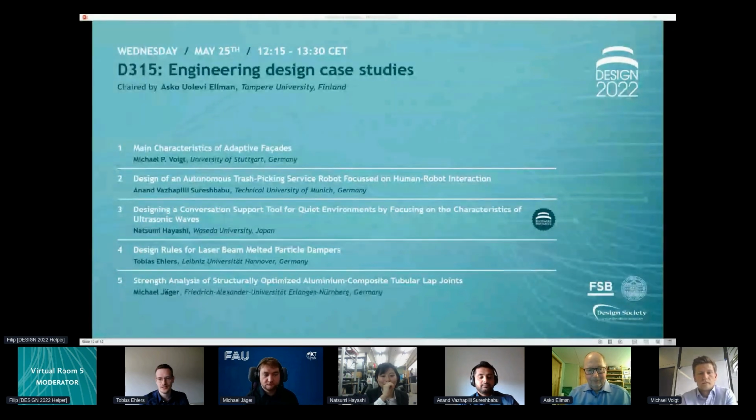So I've tried to give a little more information on how we can design the particle dampers. My key message is that we can achieve a high damping with only 2.5 or 5% of cavity volume, a damping of a factor of 14 or 15. That is the most important information.